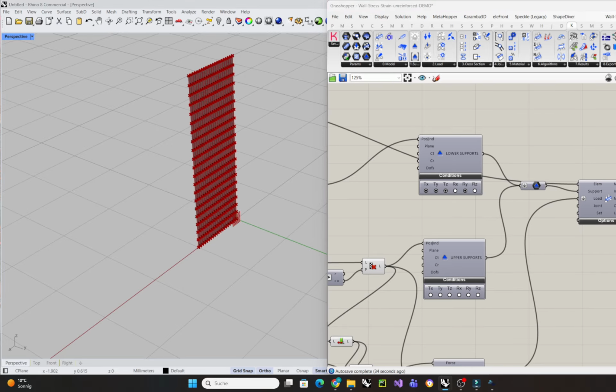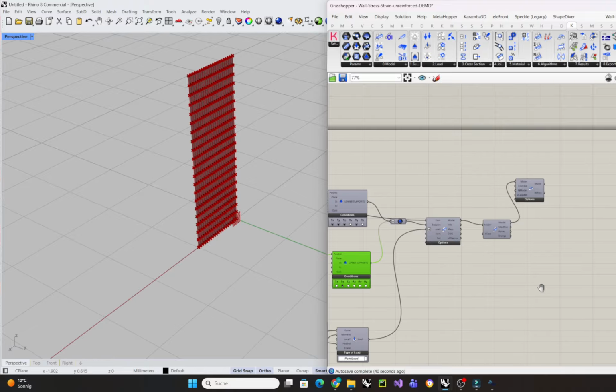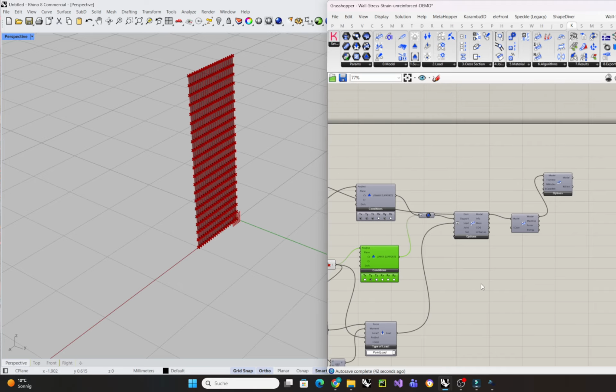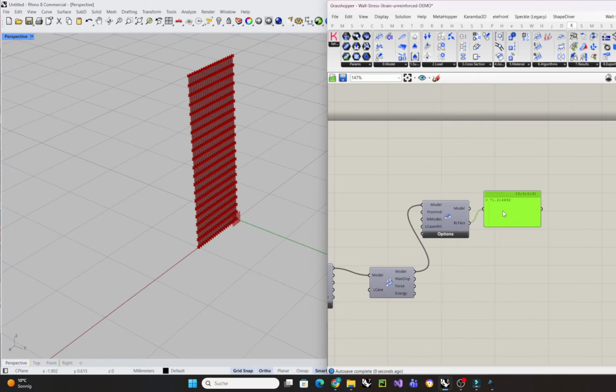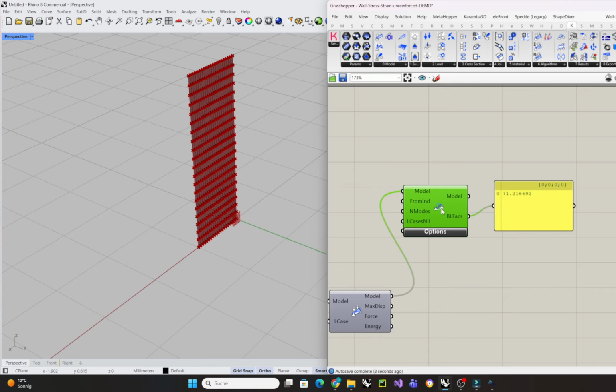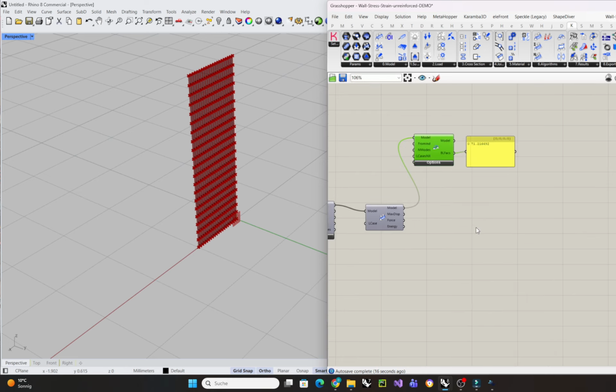And on the top I will fix only, for the slab, the direction perpendicular to the wall. And now if I check this buckling, okay, it's bigger, so this is the buckling factor, which if I multiply it with the normal force, then it gives the stability problem.